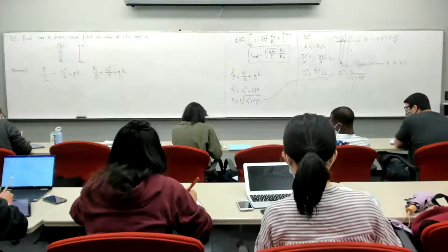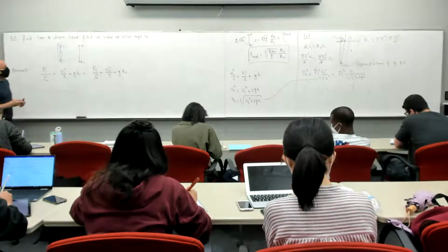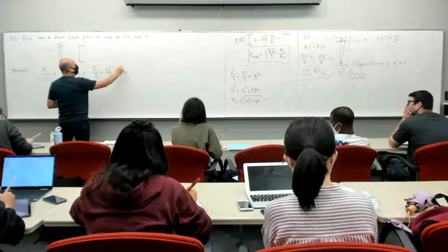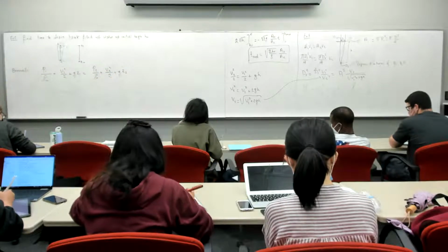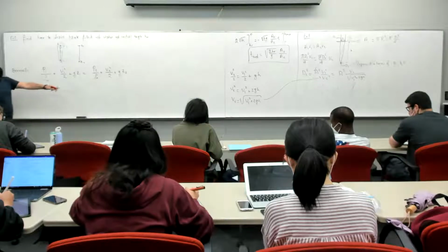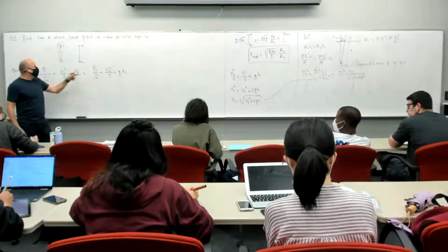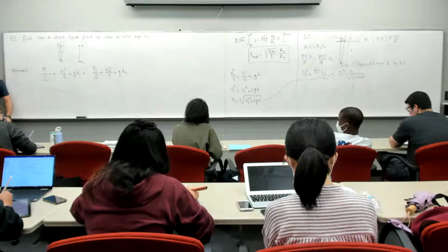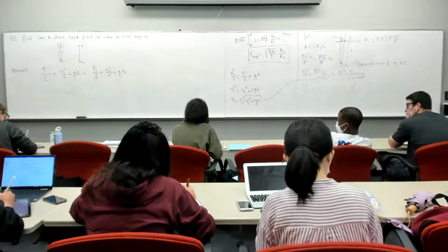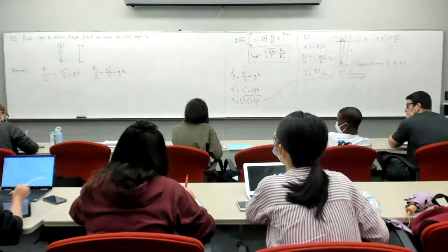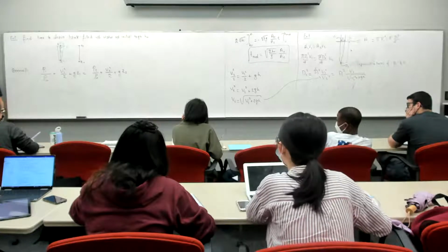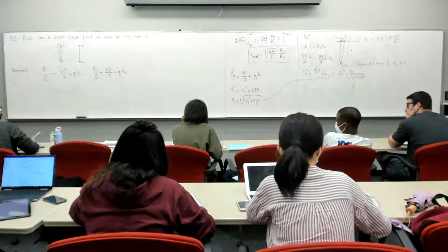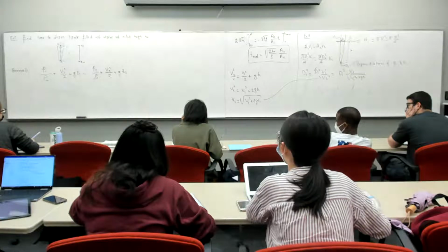What do we know and what do we not know in this equation? We know GZ1, we know GZ2, we know V1, okay? We're after V2, but do we know P2 and P1? This is not in air, this is in oil, a heavy liquid.